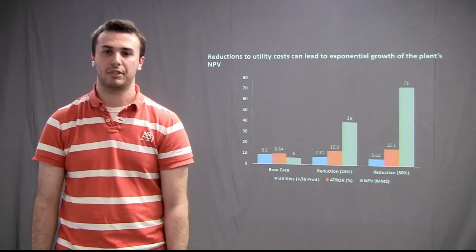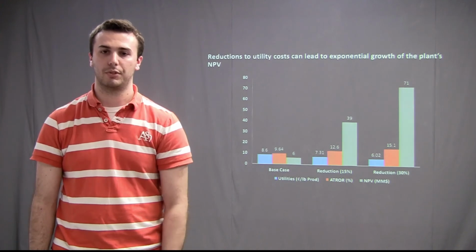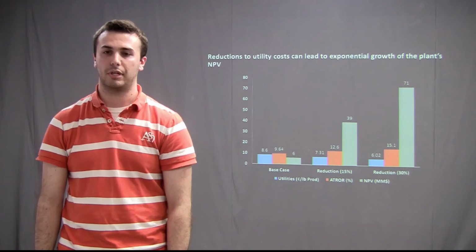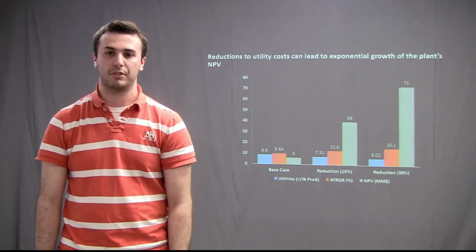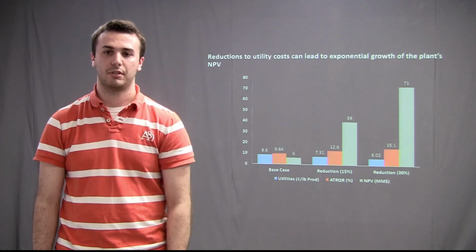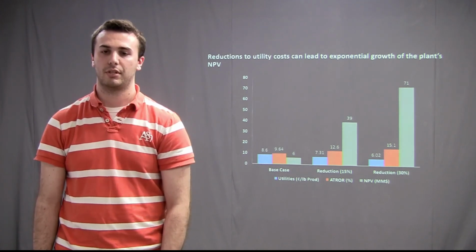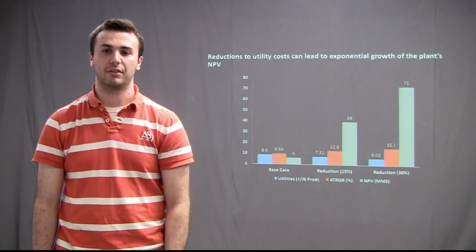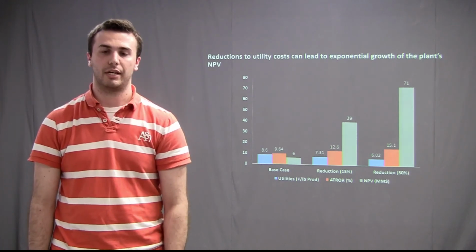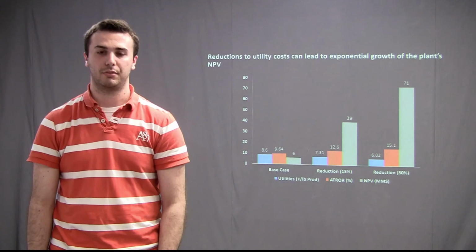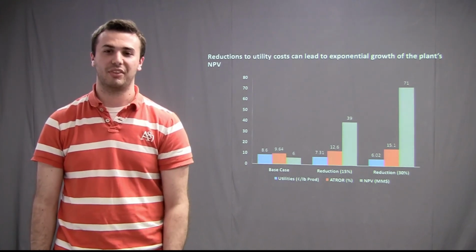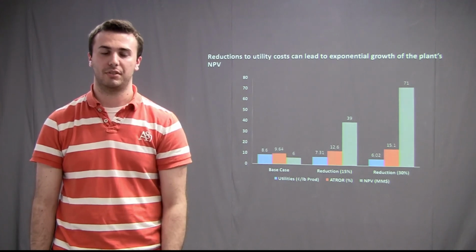A flash separation unit can be used for the ammonia and water, which will reduce the refrigeration costs for the heat exchangers. This will indirectly reduce the capital costs of the plant. Pressure swing absorption can also be researched to help replace the cryogenic distillation units for N2 and O2 separation. An alternate design for our dehydration unit from our methanator can also be used, utilizing triethylene glycol instead of the cryogenic unit, which uses refrigerants. This would be done through an absorber and stripper column combination.